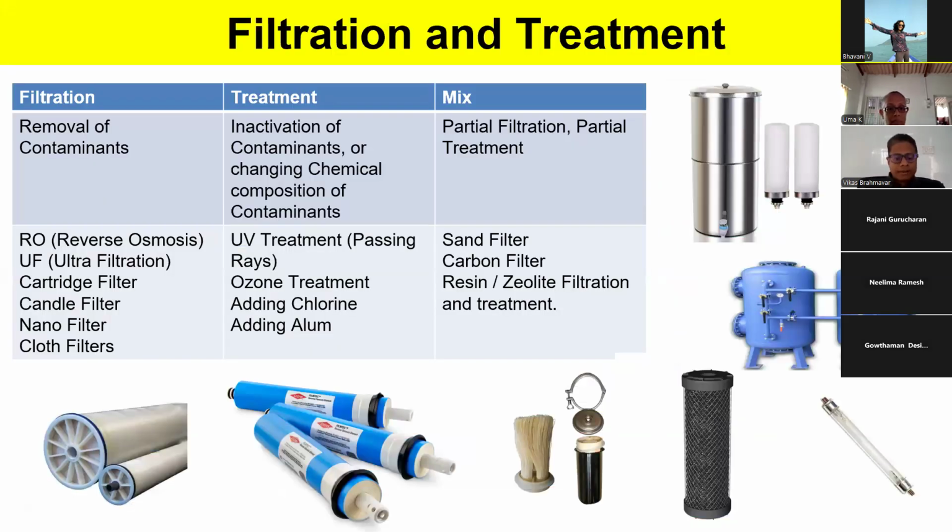Okay. Now, I would like to differentiate between filtration and treatment. This is very important because the terms in our industry get loosely used, because it's installed by people who don't get enough training to explain it fully. So we should be aware of what is filtration, what is treatment, right? What do we normally call filtration? Filtration is physically removing some contaminant from the water. Say your water is filled with leaves, it has 40 leaves in it. You put a cloth, you pour the water, you're filtering the leaves, you have water below. So that is physical filtration, right?